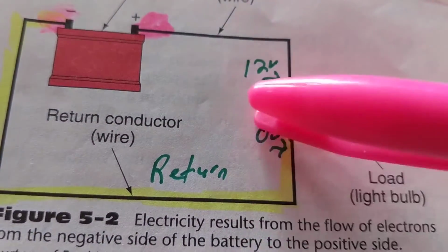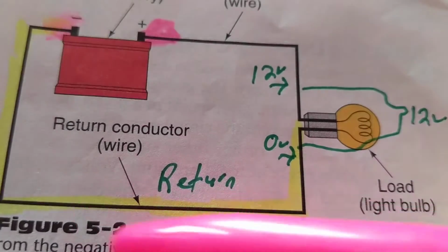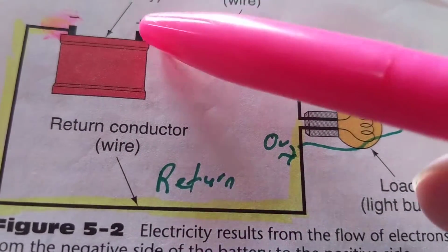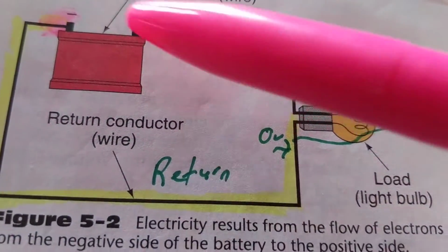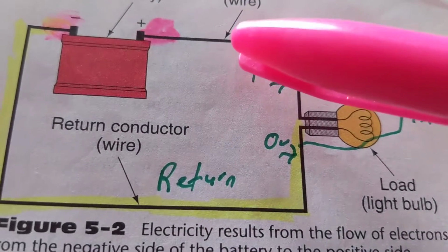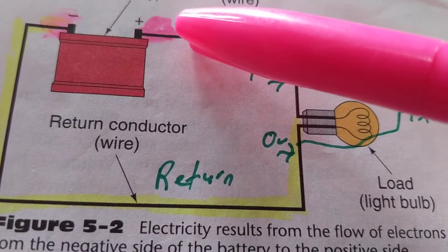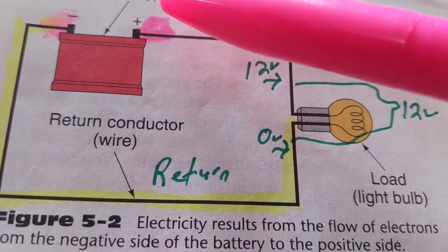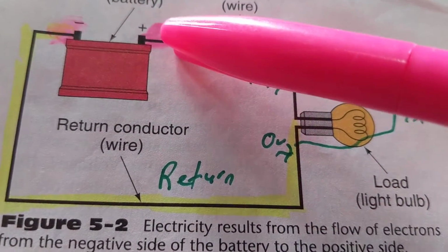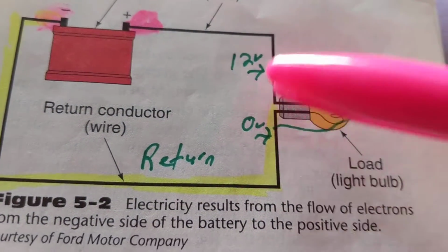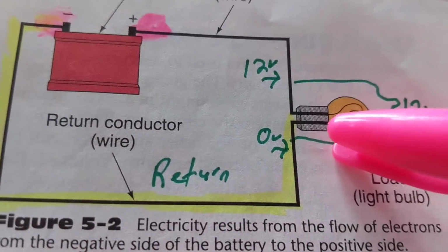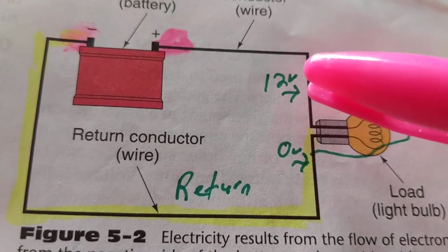Now, instead of 12 volts, guess how much he'll get? He'll get only 9 volts. Why? Because we lost. That's why we cannot afford to have any corrosion at the terminals. If you ever look, you see that plastic cover to protect the positive on your battery, because that's where the corrosion builds up. So instead of 12 volts here, this has 3 volts across it because it's high resistance. Guess what? Now it's only 9 volts available for him. He says, that's not good. I'm not going to light. I'm not going to be illuminated. We have to clean the corrosion off the positive.